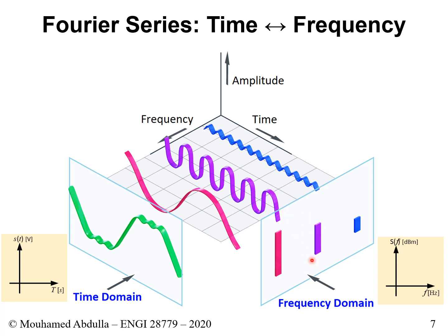This height here, again, is not the value of the voltage. It is based on the value of the voltage. It is actually a measure of power measured in dBm. This is a measure of watts, dBm watt, or sometimes we just call it dBm. And this axis here is frequency. This axis here, I mean, here they say amplitude, but in reality, when you use a spectrum analyzer, you see it in power in dBm. Okay? And this essentially is your frequency domain.